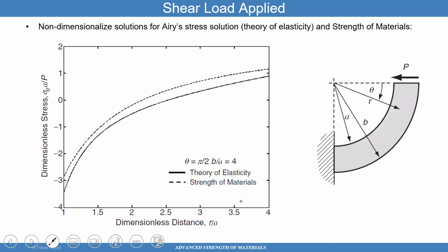Here, what I do is the same thing, but with shear load applied at the end. That shear load also gives you not a perfect match, but it's not too far away. And for this one, I won't give you anything. But if you want to try, try. But you should be able to plot this as well using the Winkler's formula and also using the theory of elasticity, because I gave you the formulas for those.